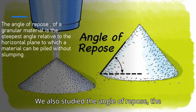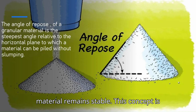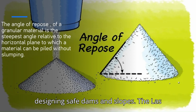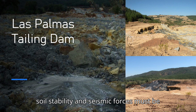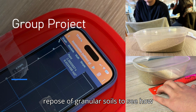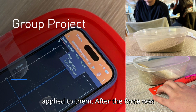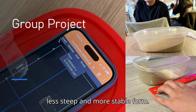I also studied the angle of repose, the steepest angle at which a pile of material remains stable. This concept is important in preventing landslides and in designing safe dams and slopes. The Las Palmas tailing dam is an example where soil stability and seismic forces must be carefully considered to prevent collapse. In the project, we measured the angle of repose of granular soils to see how loose materials can fail when a force is applied to them. After the force was applied, the sand dune settled into a less steep and more stable form.